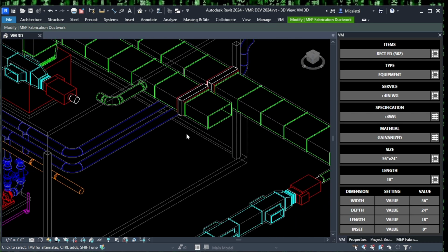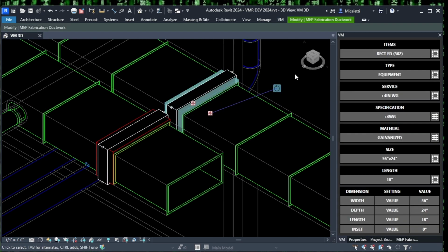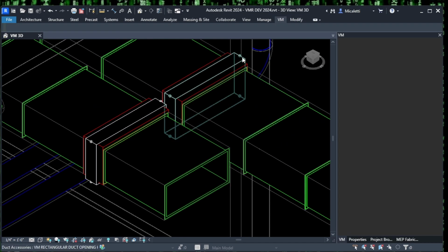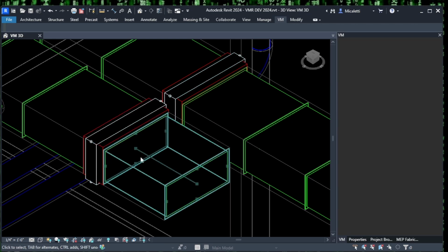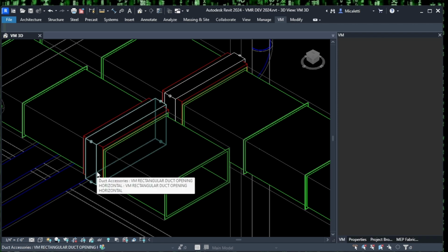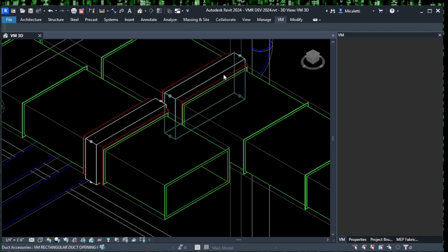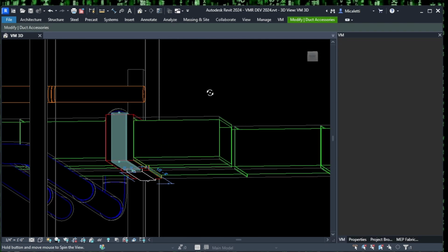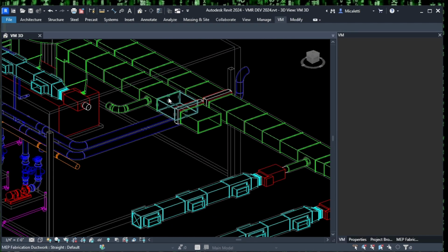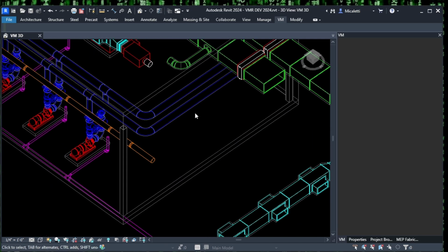Are those fire dampers in your fabrication palette, or are those independent families? These are actually ITMs. This is CID 502, and it's one of the ITMs that we do support. It will do families as well, but fire dampers are weird in that they have a hat, right? The connector's not necessarily centered on the opening. If you use CID, it is going to be smart, but it may not work how you're expecting if you use a family, but you can sleeve families. So that's a good question.